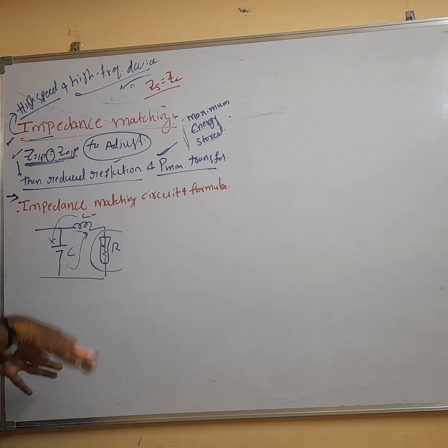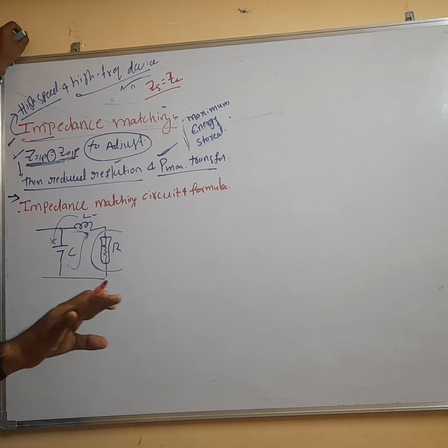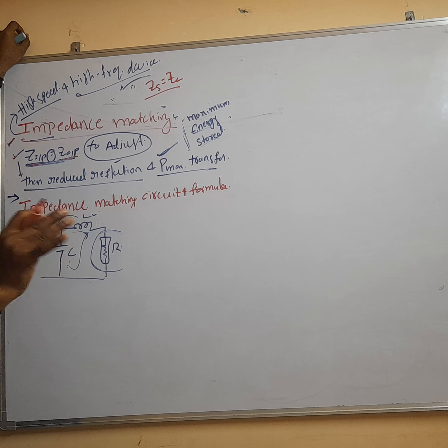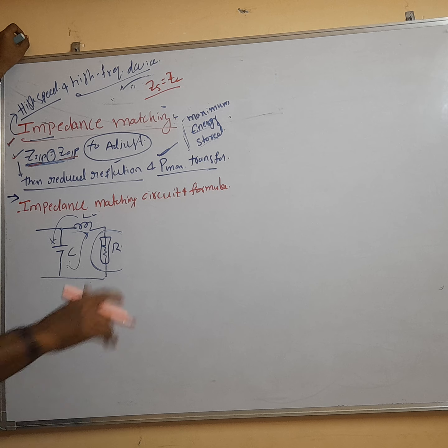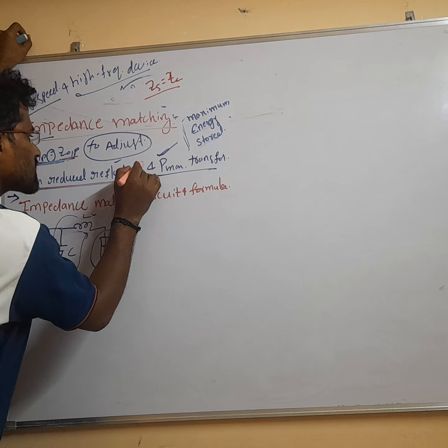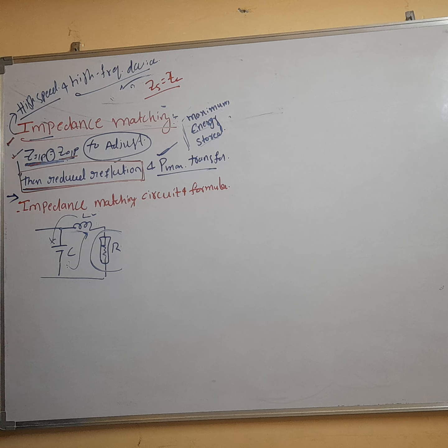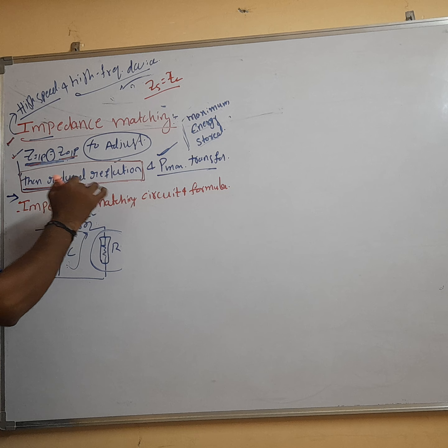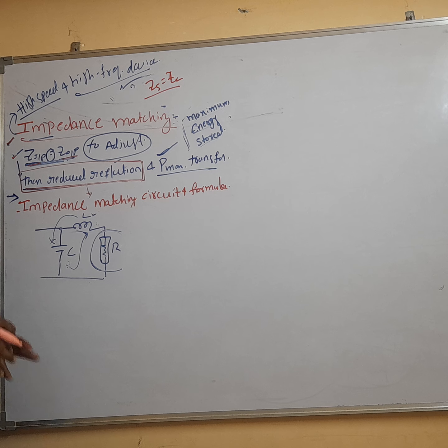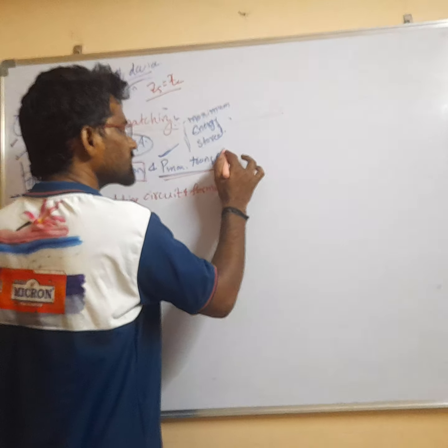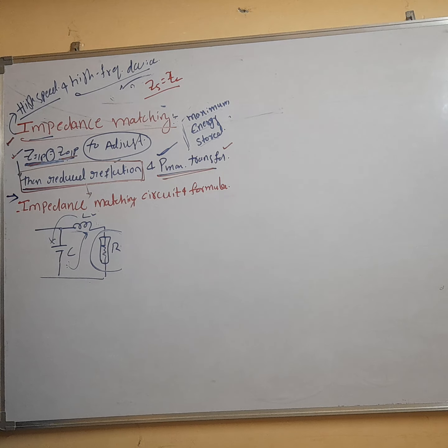If we maintain impedance matching, the source and load impedance must both be the same. What happens under this condition? First of all, the reflections in electronics and communication systems are reduced. Similarly, the maximum amount of power will be transferred from the source side to the load side.